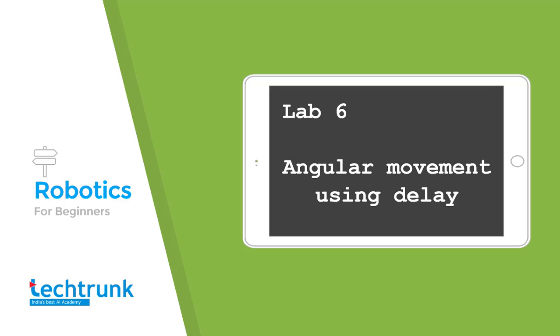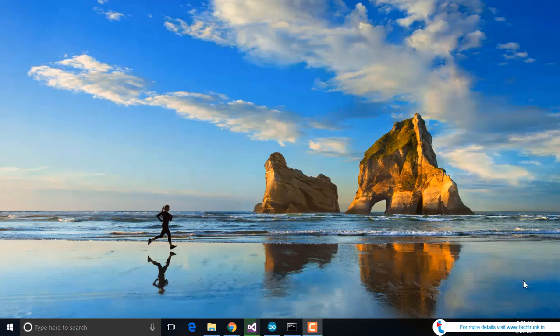For this case, we'll be sending simple instructions to the robot, and based on that, every instruction will be programming the robot to take a turn with certain times of delay. You might have already noticed that when you ask a robot to take a right direction, it keeps on turning right unless we stop it. So if we can control the time for which the robot is turning right or turning left, we can control the angle that the robot is taking while turning right or turning left.